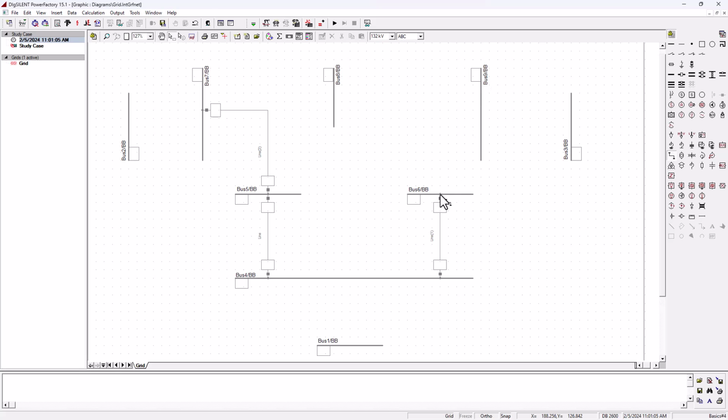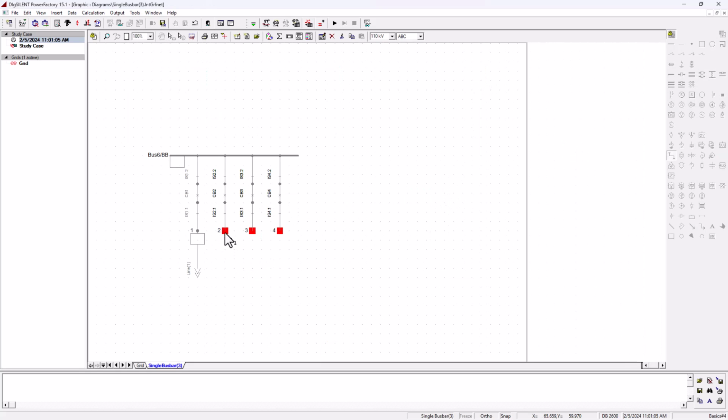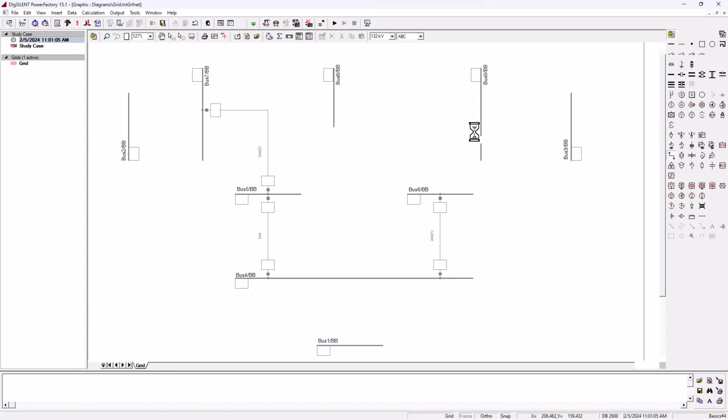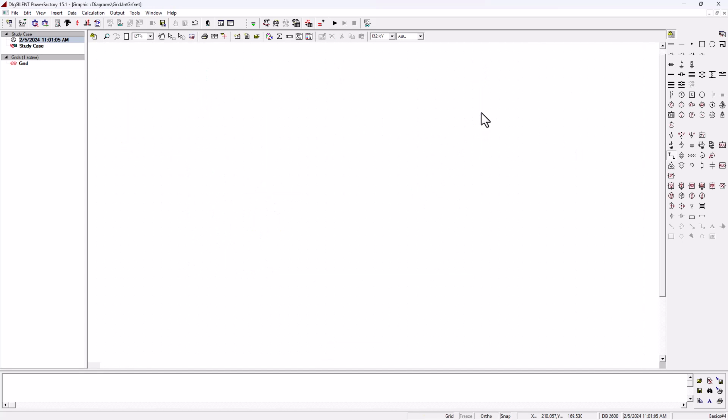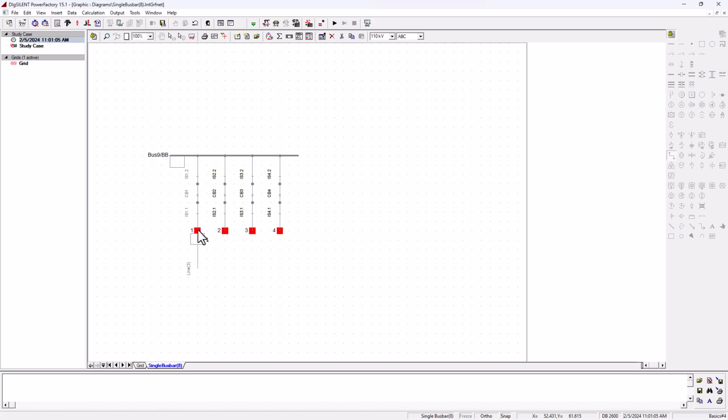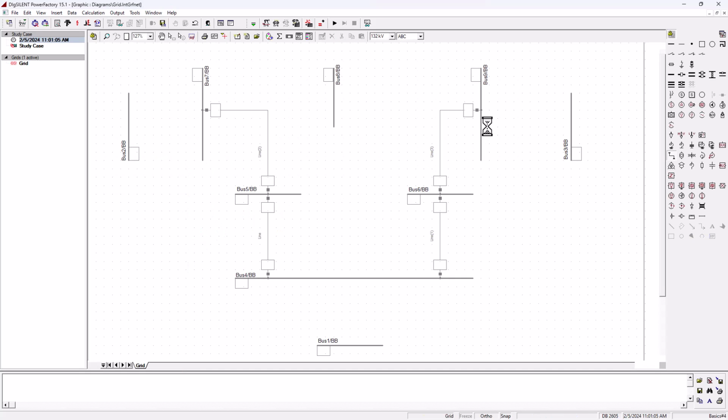So we're going to click on bus bar 6, take the cubicle 2 connection, and bring it to cubicle 1 of bus bar 9. Great, so the connection is done there. Now what is our next line? So that is line 7 to 8. Where is line 7? This is line 7, so you basically must connect this way.